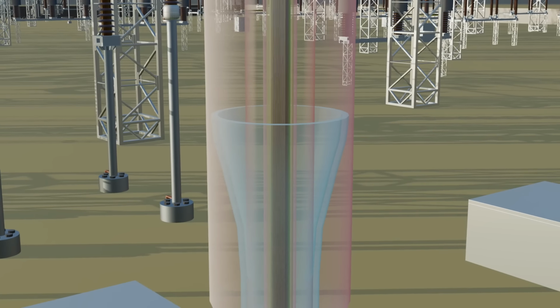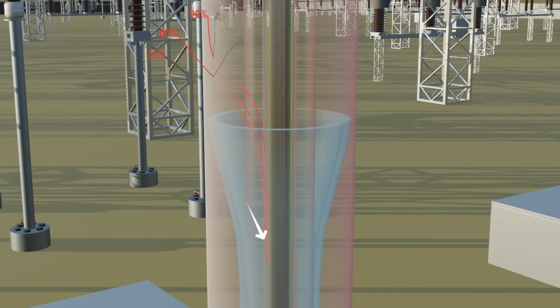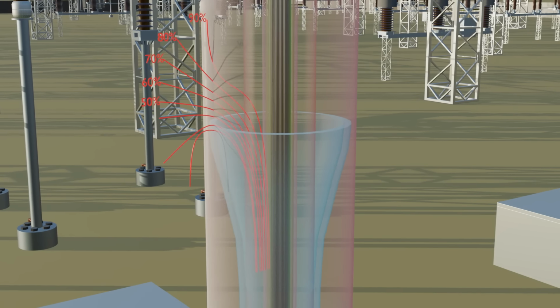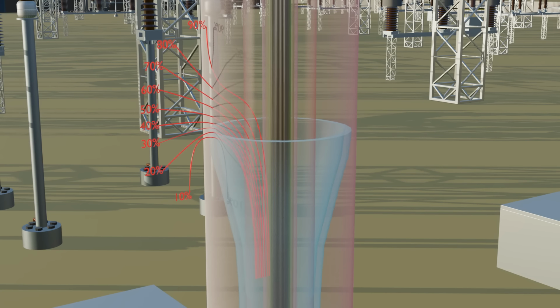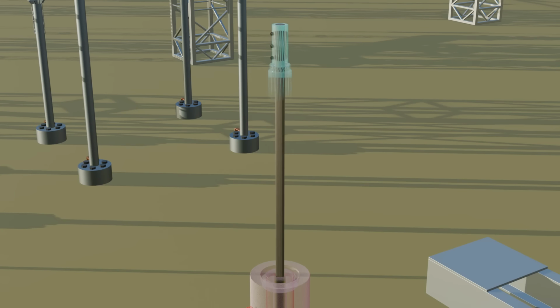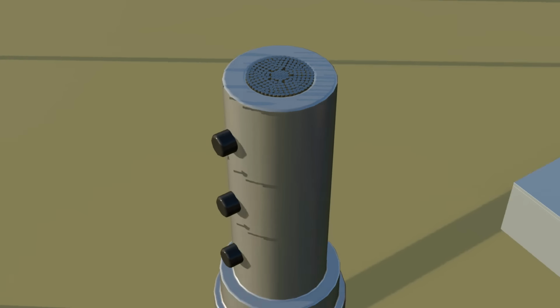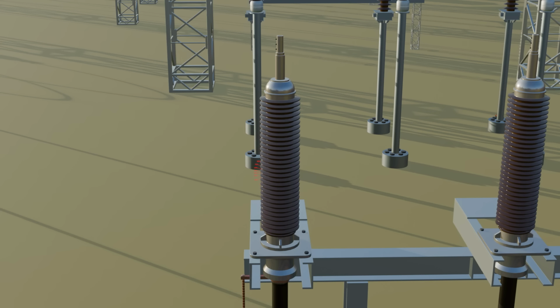The field is strongest at the point where the cone touches the insulation. As we move further away, the field gradually reduces. This creates a smooth voltage gradient and helps control the electric field. Here, the metallic sheath is properly earthed. After this, the conductor screen is removed, and the main conductor is connected to the connector. Finally, the external insulator housing is fitted over the stress cone and conductor assembly.